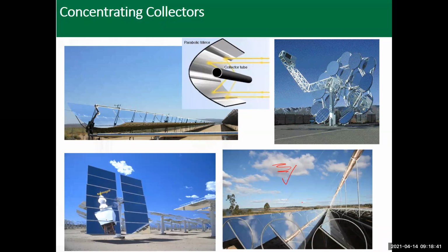The length of the Fresnel lens that they have used is somewhere, I think, something like 100 meters or so. So the fluid gets in with a normal temperature, and then as it's moving in here, it ends up with an exit temperature of about 350. They take this temperature in a heat exchanger. So the oil is going to lose its heat in the heat exchanger before it comes back here again to be reheated. And in the heat exchanger, the other fluid is water, and water is being converted into steam, and the steam is used in a Rankine cycle for producing power.